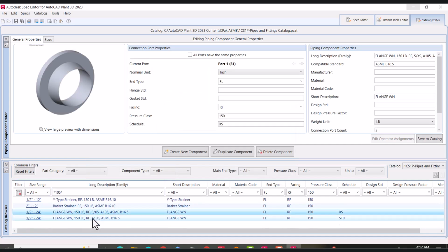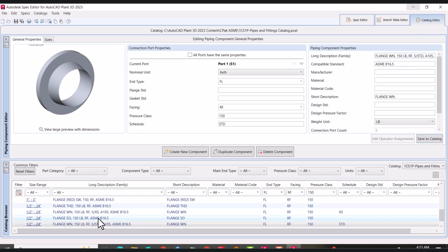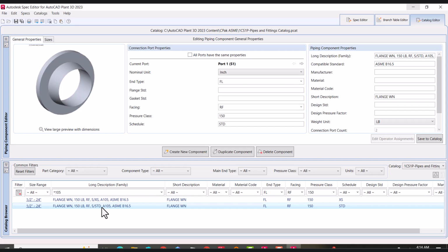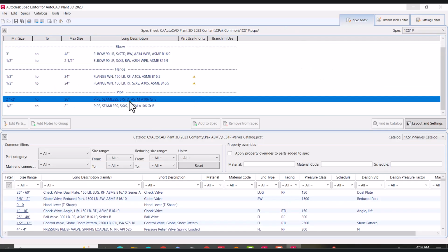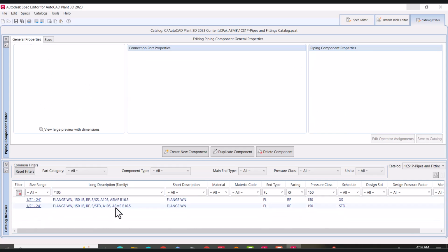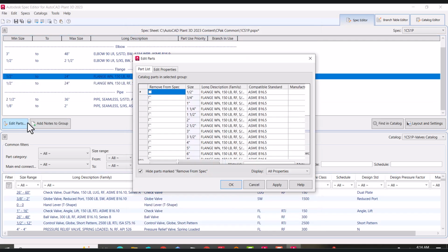So one time you just spend the time and create the specification carefully, because they are going to be with you for a long time, and they will be affecting your output. For example, if you mention the wrong description, it will come on the BOM, and ultimately it will be reflected on the drawings. And every time you'll have to do the manual changes. So better just prepare the specification correctly.